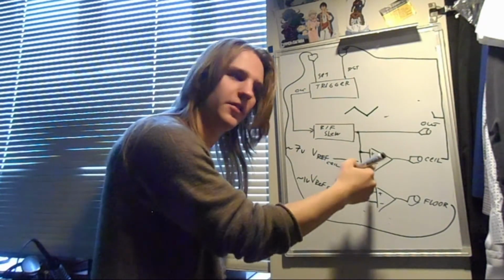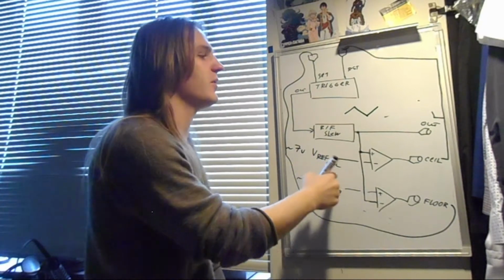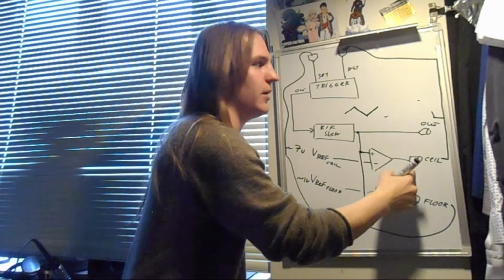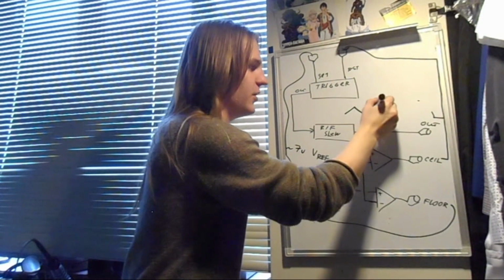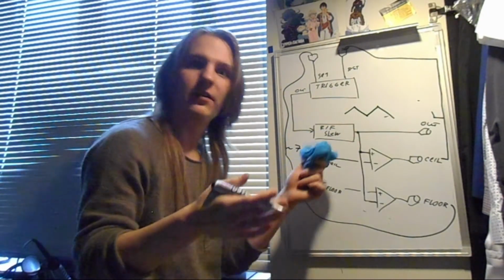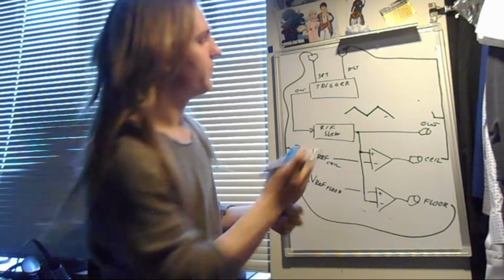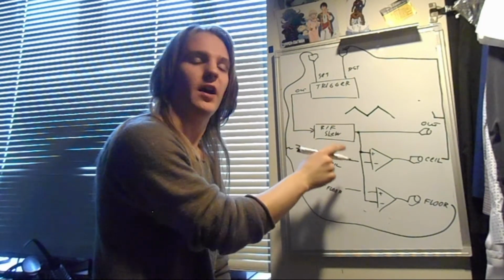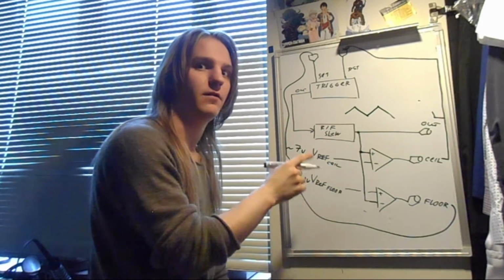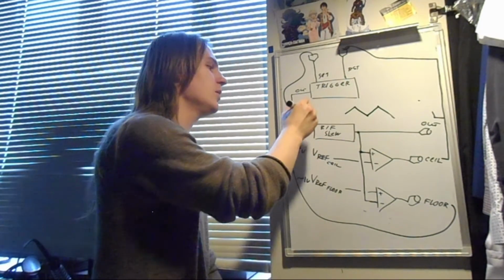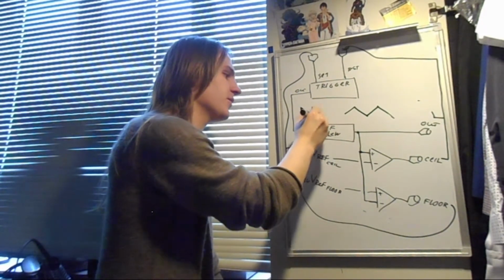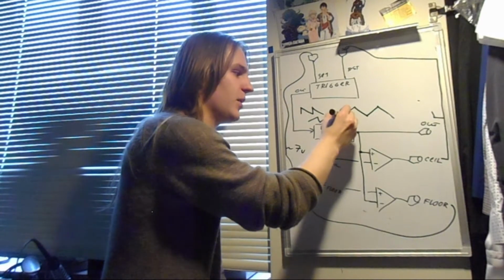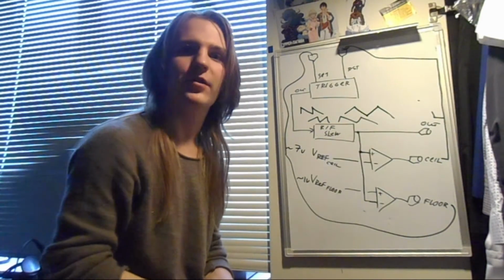Then it charges until it reaches the voltage reference ceiling, and the ceiling comparator resets the function and it starts falling back. We have an LFO. By trimming the attack and release, or the rise and fall values on the rise fall slew, we can make it look like this, and something in between. Very interesting.